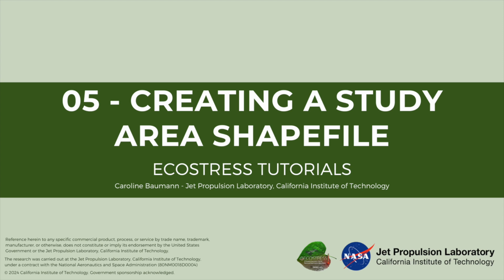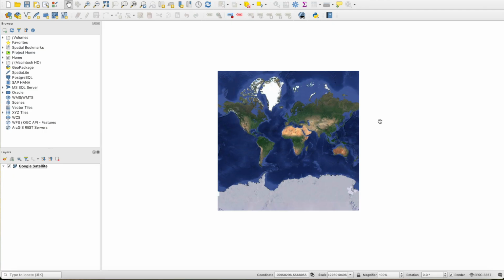This tutorial will teach you how to create a study area shapefile in QGIS. A shapefile is a type of vector data format that can be used to store geographic information. We can use it to define our study area. This is helpful because we can use it to download ECOSTRESS data either from AppEEARS or Earth Data Search.